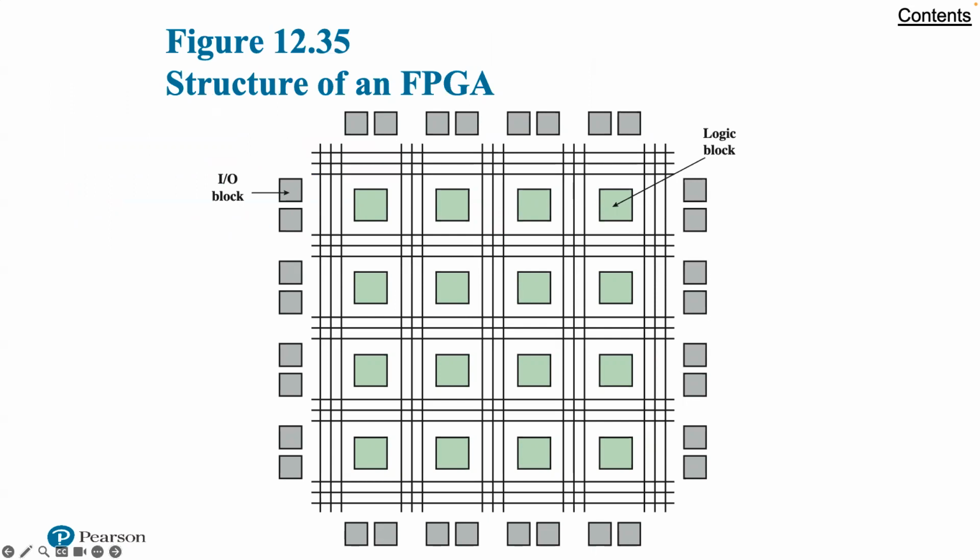The difficulty with increasing capacity of a strict SPLD architecture is that the structure of the programmable logic planes grows too quickly in size as the number of inputs is increased. The only feasible way to provide large capacity devices based on SPLD architecture is then to integrate multiple SPLDs onto a single chip and provide interconnections to programmably connect the SPLD blocks together.